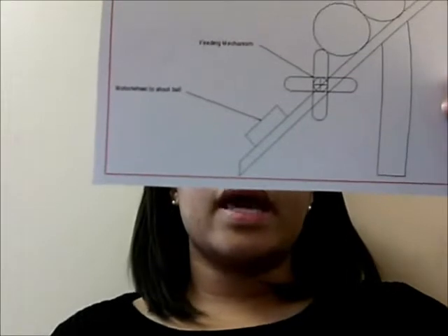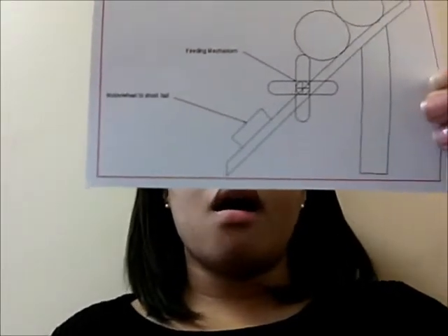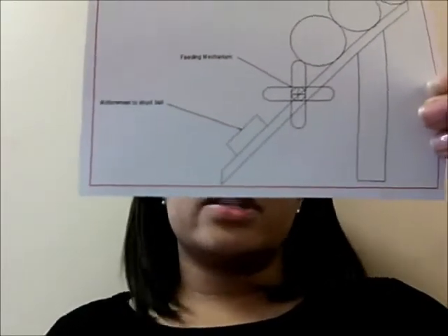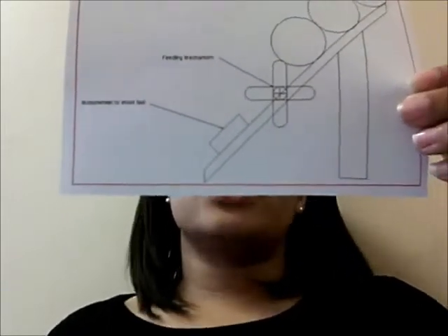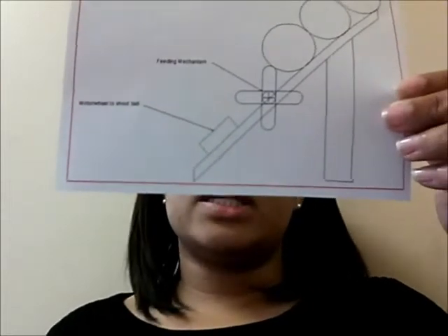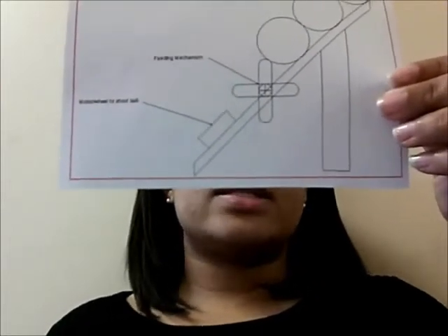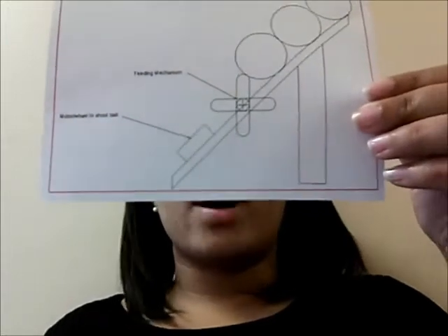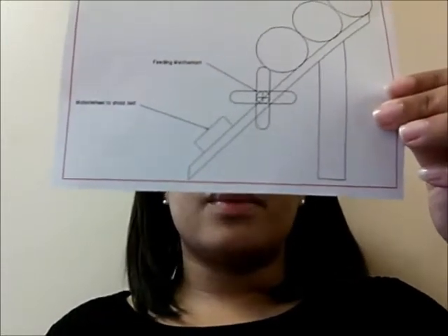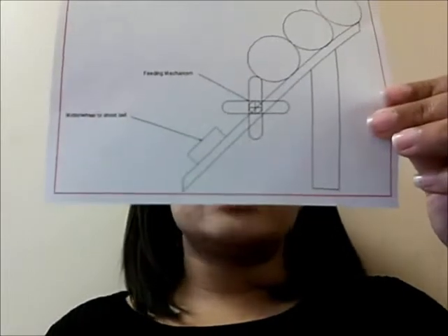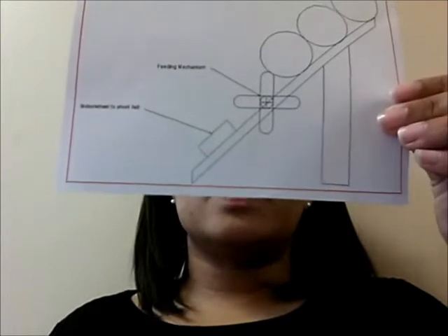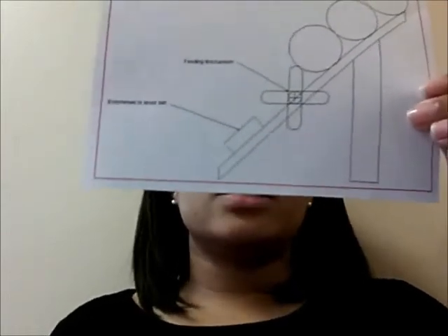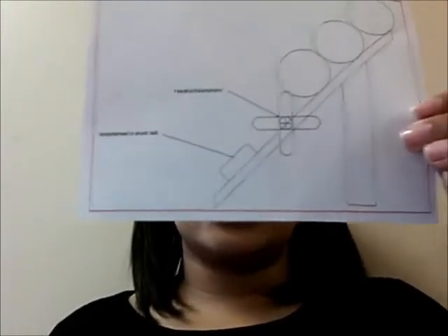So the balls will be held all the way up the rail. We will then use a servo motor that will release the ball at the correct time. Software will control the motor to release the next ball being shot. The servo motor will step just enough to let one ball release down the rail to the motors that will shoot the ball. The rest of the balls will be stopped until the next ball needs to be released. We will use the potentiometer as we did in Research Project 2 to find the correct position the motor needs to be in order to release the ball.